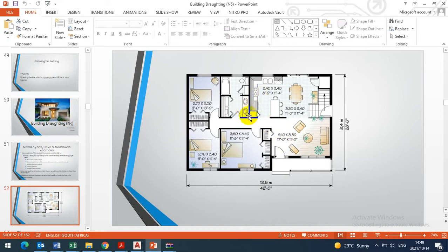All right. Then coming to plumbing installations like the bath, the shower, the sink in the kitchen, toilet, those count for marks. Make sure that you also take them from the library. That is a must. You have to show them. Even if you don't show furniture, you won't lose marks. But plumbing installation, you must indicate on any floor plan.